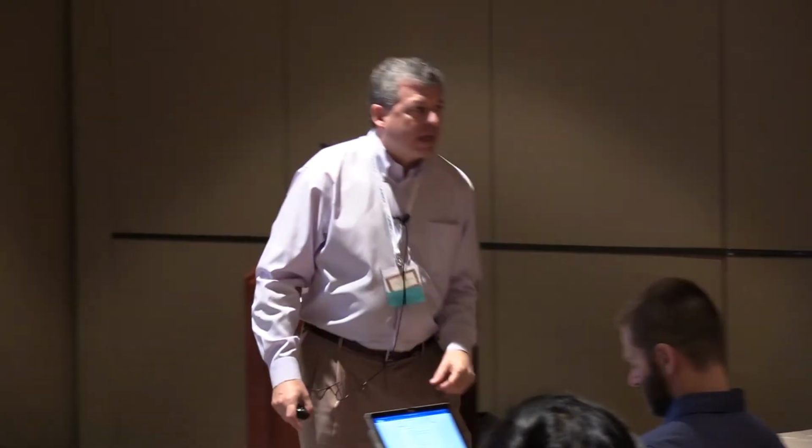That's a little different than mimicking daylight. It's really more of a style, but it also is appropriate because if you have a desk in front of you and you want to get a certain amount of light on the work surface for you to take notes, to work on a computer, to have a meeting, the flexibility of space allows me to adjust the light. If I had darker walls in this room, the amount of light potentially on your work surfaces might actually be different if I didn't make an adjustment to those lights. So if I change it from a tan wall to a black wall, I might actually have to increase my light and potentially my color temperature to make that work.